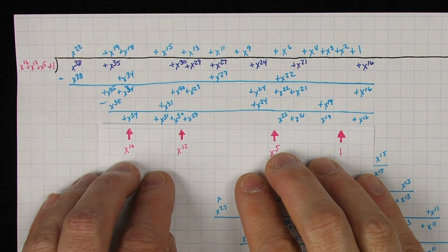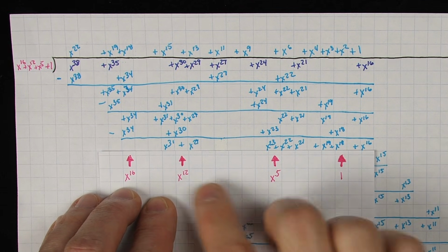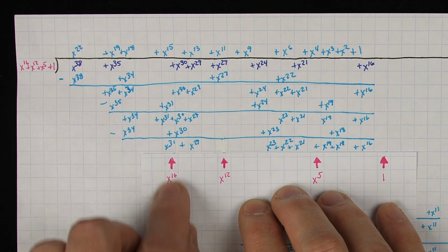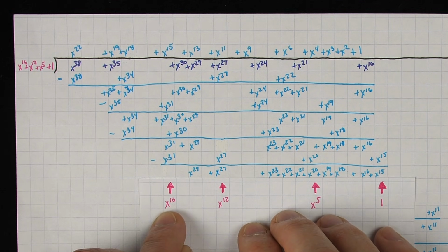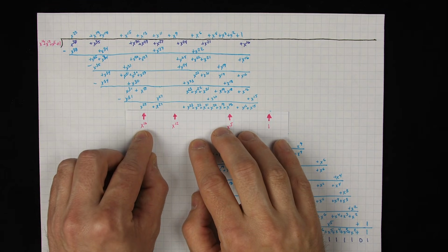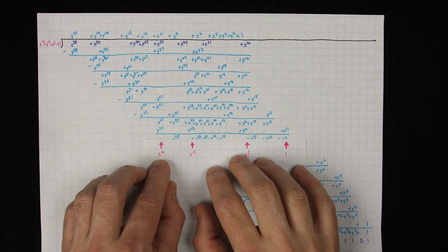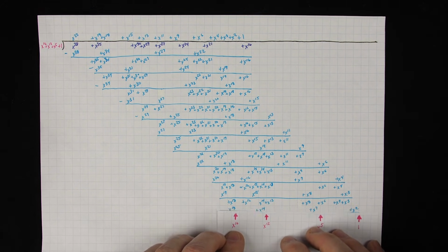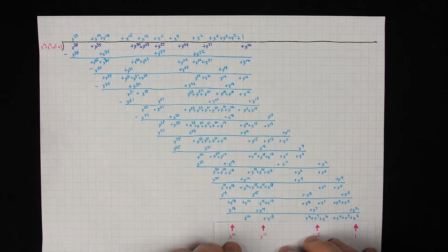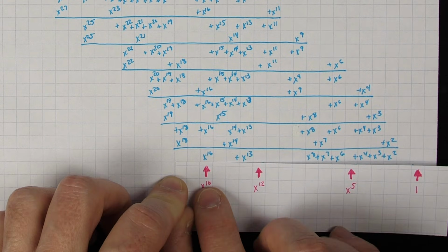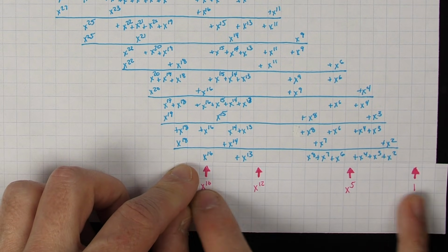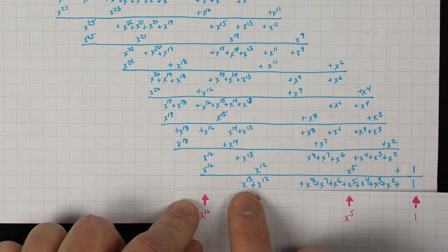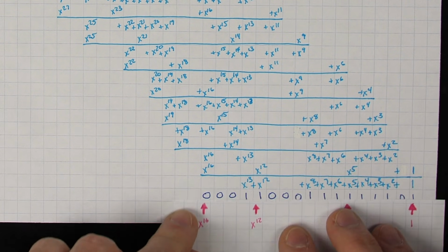And then we just slide over to the right, flip those 4 bits, and we end up with a new polynomial here. And then we can keep sliding until this x to the 16 lines up with a term, and then flip those bits. And we end up with another polynomial. And we just keep doing this, sliding, flipping those bits, sliding, flipping, until eventually we get to the point where we slide over, and now x to the 16 lines up with the x to the 16 place. So we've slid essentially as far over as we can. We've gotten all the way to the end, and then we do that final flip, and this polynomial that we end up at the bottom there, that's our CRC.